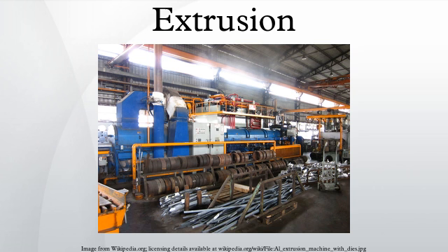Warm extrusion is done above room temperature, but below the recrystallization temperature of the material. The temperature ranges from 800 to 1800 degrees Fahrenheit. It is usually used to achieve the proper balance of required forces, ductility and final extrusion properties.